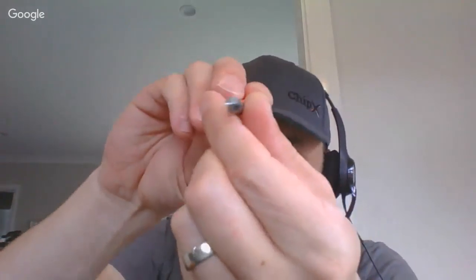If you want to Google it, chip thinning is an interesting concept. The basic idea is that when you are running a cutting edge through the material, you can start by taking quite a thick bite. I sometimes think of it like a digger bucket biting into the dirt over and over again.